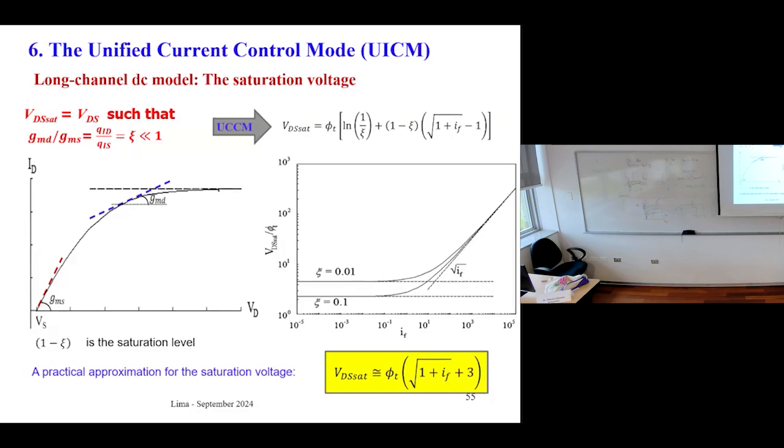This is basic theory of MOSFETs in the strong inversion region. But for weak inversion, look, the saturation voltage does not depend on the inversion level. If it's 0.001 or 0.01, or up to 1 approximately, the saturation voltage of the MOSFET is around 100 millivolts. So designs for low voltage sometimes or most of the time employ transistors in the weak inversion region or subthreshold region.